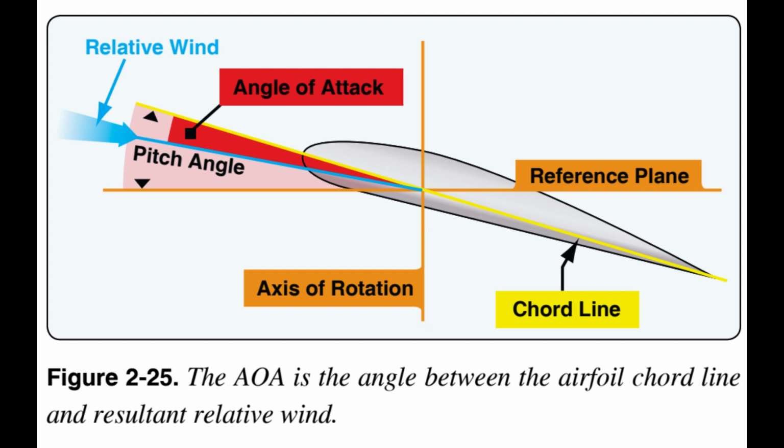Cyclic feathering causes attitude of the rotor disc to change but does not change the amount of net lift the rotor disc is producing. Most of the changes in AOA come from change in airspeed and rate of climb or descent. Others such as flapping occur automatically due to the rotor system design.